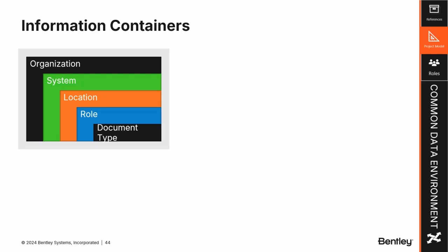It just has those two key principles of breaking it out into logical information containers and then working each through a QA/QC process and then federating them back together. So the UK 2019 addendum to ISO 19650, it gives us one way, or the way that the UK government would rather do it, and that's what we're using for our project here.